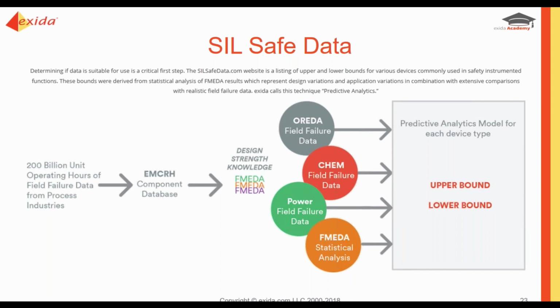It's not going to say specifically this product, but it will give you a low bounds and an upper bounds on what to use for failure rates. So this is a great website, even if you have your FMEDA. I always say no matter who gives you failure rates, always check them against this. Make sure what you're getting matches that sanity check. Make sure you're never given a red flag.